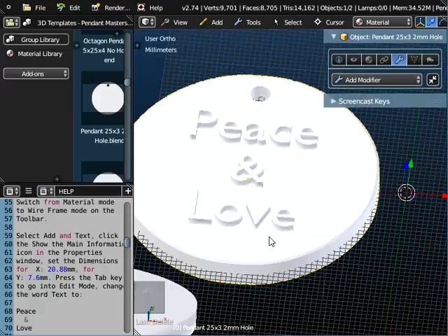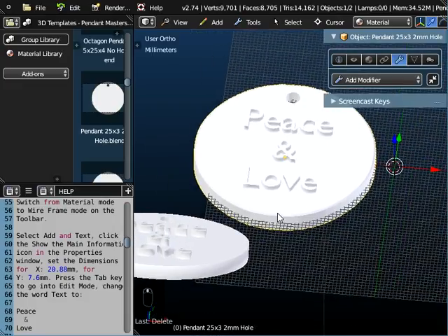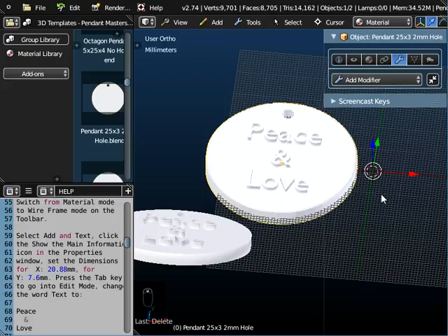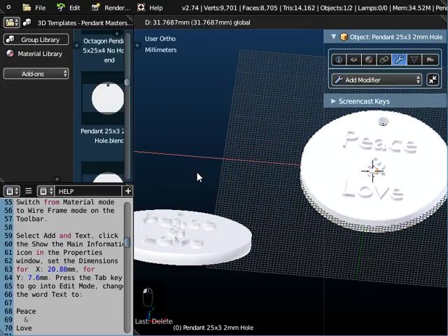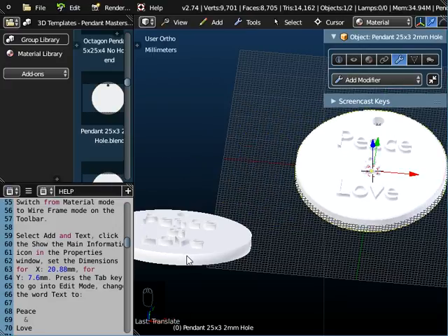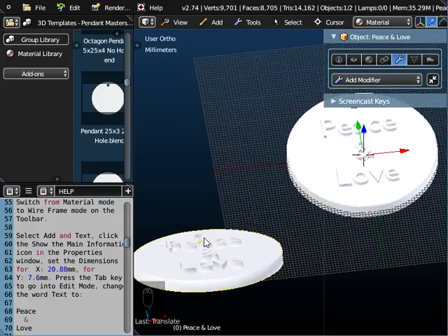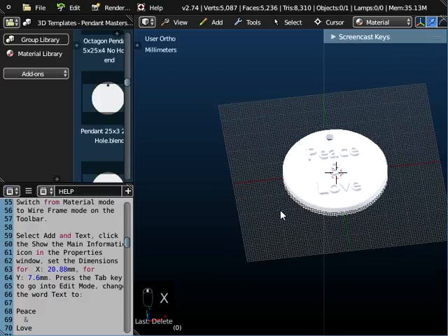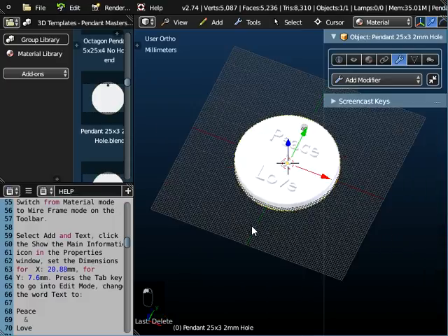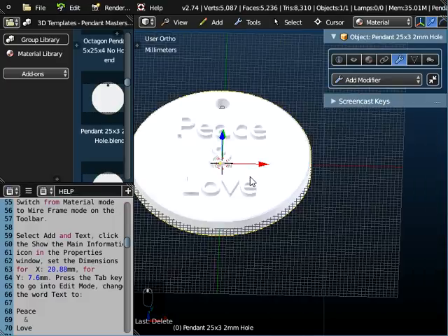We still do need to run it through Netfabb to probably fill in a few holes and border edge problems. It's the usual sort of thing that we get with FluidDesigner. So we just put that back in the center. We'll highlight the original one that was on the screen when we started and press X on the keyboard and delete that one.